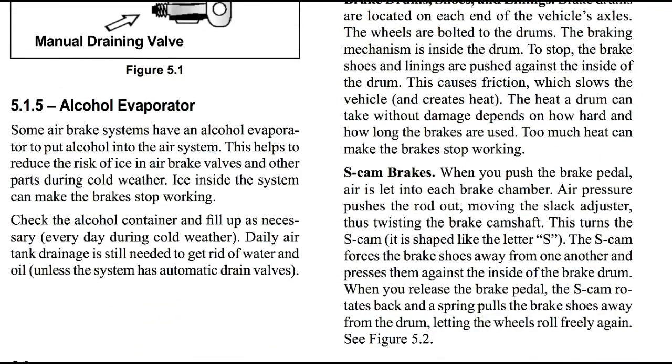Alcohol evaporator. Some air brake systems have an alcohol evaporator to put alcohol into the air system. This helps to reduce the risk of ice in the air brake valves and other parts during cold weather. Ice inside your system can make the brakes stop working. Check the alcohol container and fill up as necessary every day during cold weather. Air tank drainage is still needed to get rid of water and oil, unless the system has an automatic drain valve.